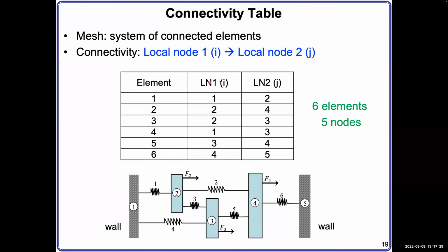Good. So now in this case, to solve the force there, we need to use the force equilibrium condition. Each spring is in a force equilibrium. Each node is in a force equilibrium. By listing their equilibrium equations, we will have a set of equations, and then we solve the equations one by one, and find out the unknowns there, which are the force and displacement.